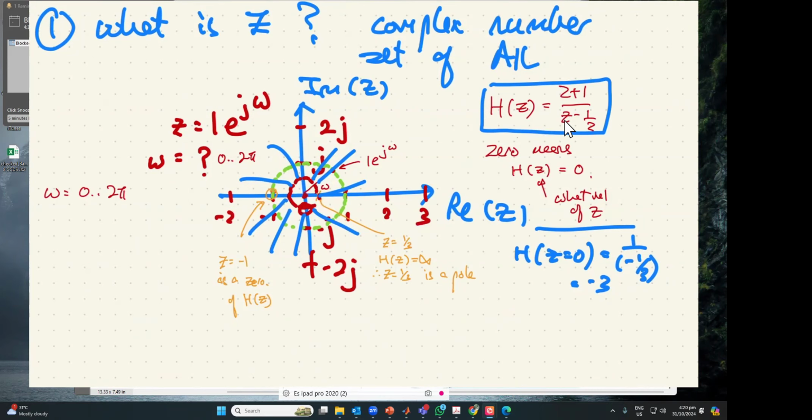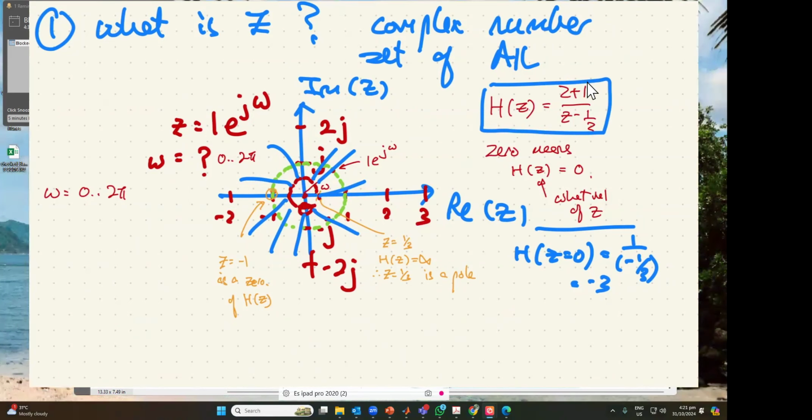Every time I give you a closed form expression, you must know the region of convergence. What values of z will be correct in representing this? If you put it outside the region of convergence, although you can get a number, it is totally wrong. Okay? So please remember that. So that was a trick question just now when I asked you to substitute z equals 0. You all happily substituted z equals 0, got minus 1/3, and this is rubbish. All right?